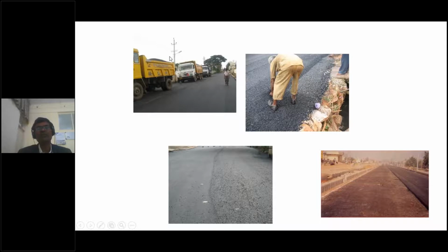I was telling, keeping the mix for a longer duration is also not good. It kills the life. And look here, this joint is also not straight, not uniform. On this side, you can see it should be something like this. So this improper joint, and any joint for that matter, whether concrete pavement or asphalt pavement, is a weak plane. The first distress always appears in the joints.